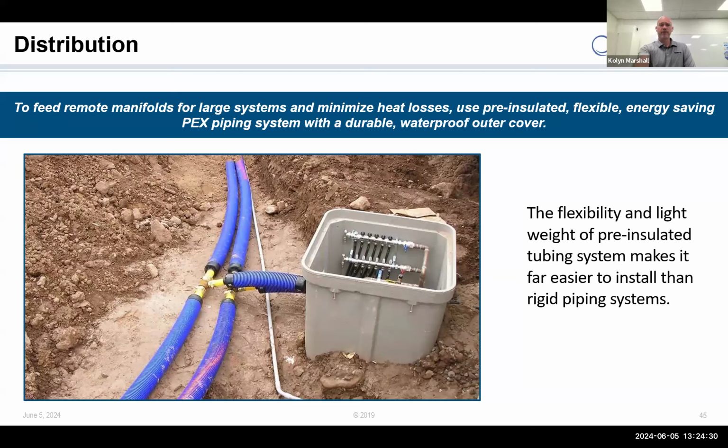Normally, the manifold would be the highest point. That's ideal. Manifolds have the vent purge on them. You just purge from the manifold highest point, ideal. In that case, where the tubing is the high point, you don't have that luxury. So what we typically recommend is what I have referred to over the years as a power purge.